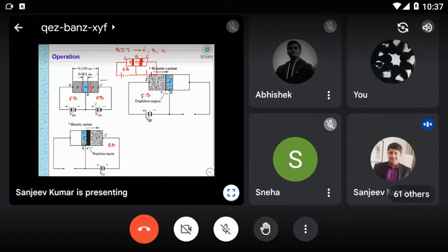Now if you go for total current, the total current will be I majority plus I minority. Sometimes it is very less. Already I told that leakage current is small. So whatever current flows from emitter to collector is due only to majority carriers. Okay.